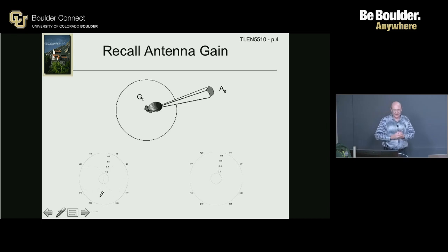This is the antenna pattern of what? Anyone recognizes this? The one at the bottom? Dipole. Very good. A dipole that's basically vertical here, and that's fed by 2 wires, and basically the signal feeds that dipole, and that dipole doesn't transmit anything up or down.